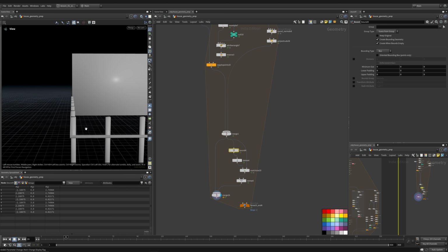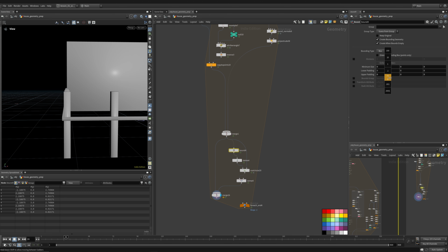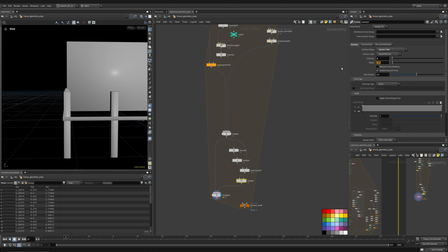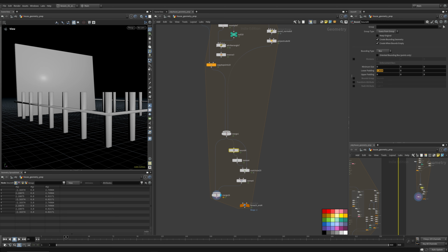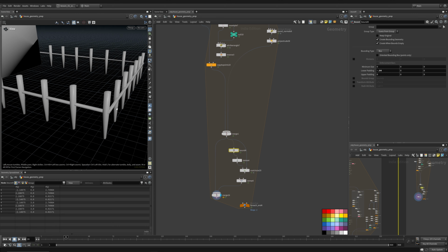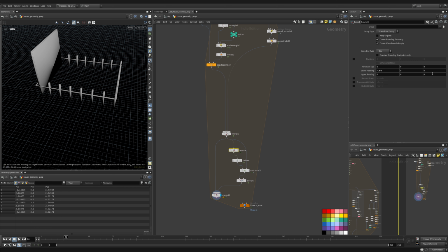So if I select down here and then select this bound, by decreasing this with a negative inner padding, you can see it slides that plane inside. So we'll do negative 0.01, which is not enough. 0.05 is our width, so let's do negative 0.025. That would make it even, but we don't want it exactly even, so let's do negative 0.04. There we go. Now it's inside, and we'll do the same thing on the Z,